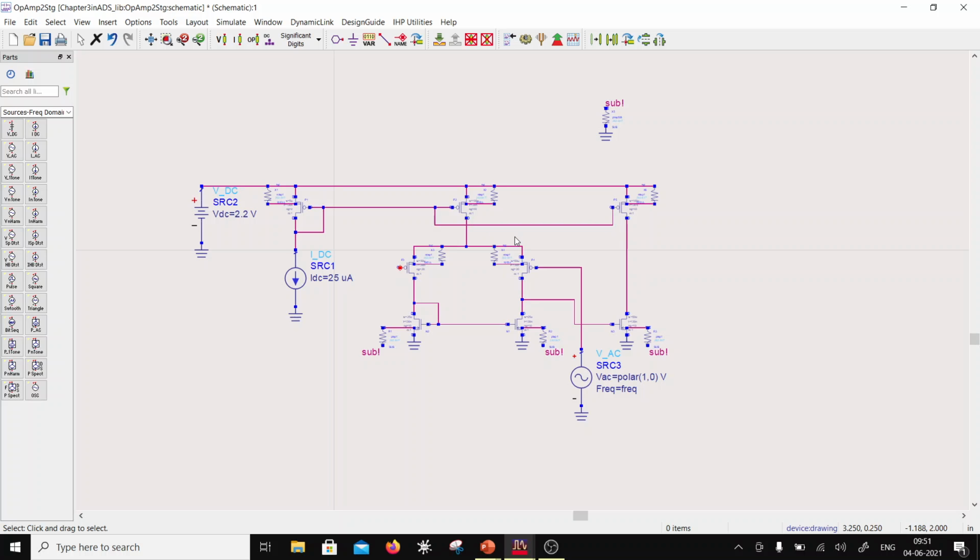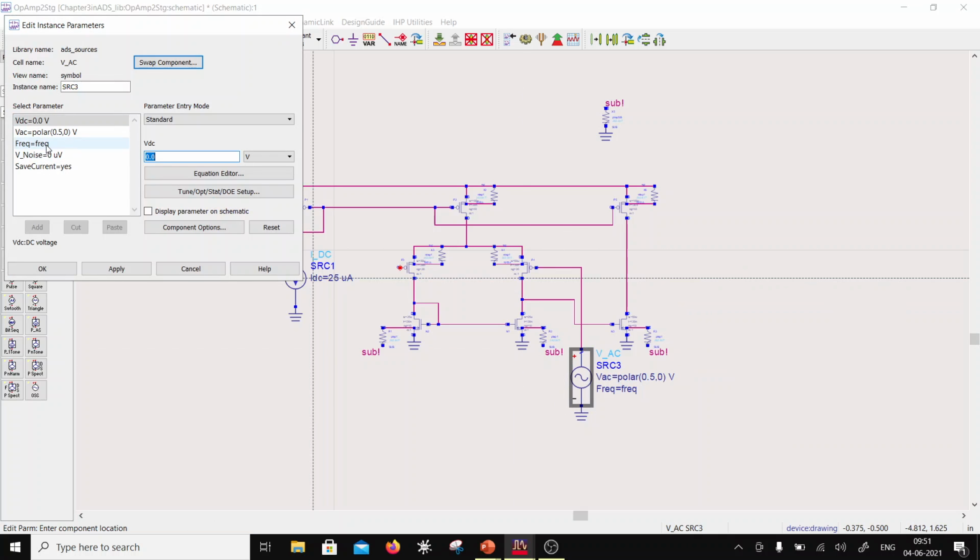That is going to be 0.8. So 0.8 from here is going to be 1.4. So I can give it easily, because the common mode voltage range is large, a DC value. So there is a DC value over here. I can give it a DC value of, let's say, 1 volt, and I will display this, right?